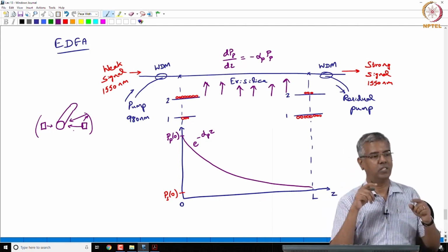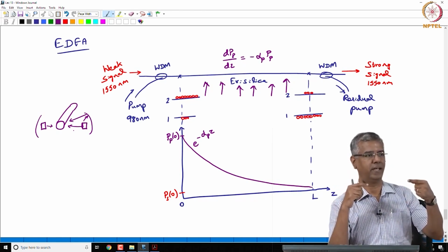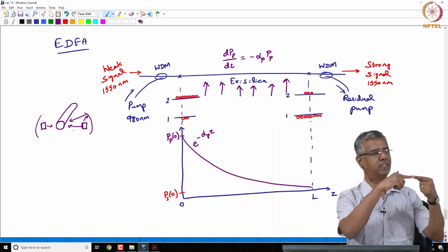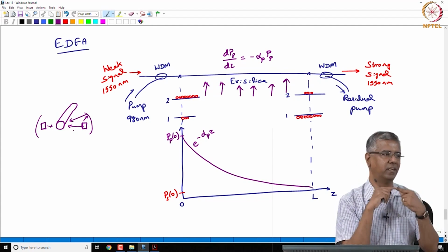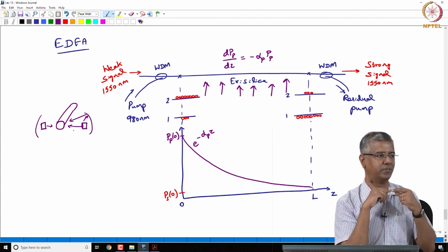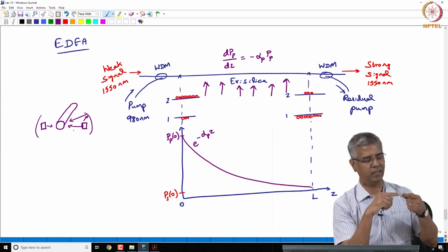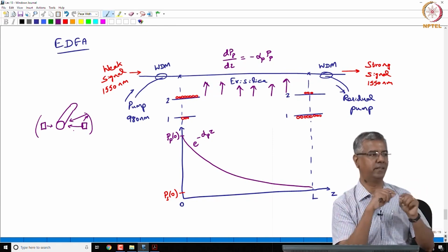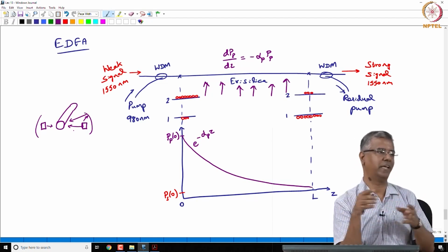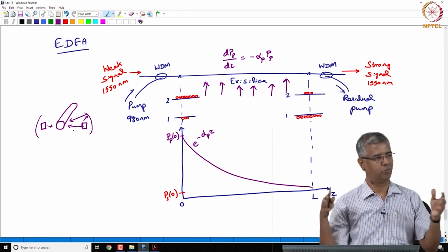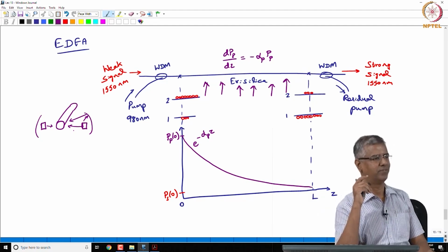So, you have the possibility of taking the fiber. If this is my semiconductor laser, I take my fiber and just directly butt couple it against my semiconductor diode, right. So, I just hold it right against that aperture, so I can couple light directly. I do not even have to think about taking the light out and having some focusing optics and coupling it, because the packaging would be a mess, right.